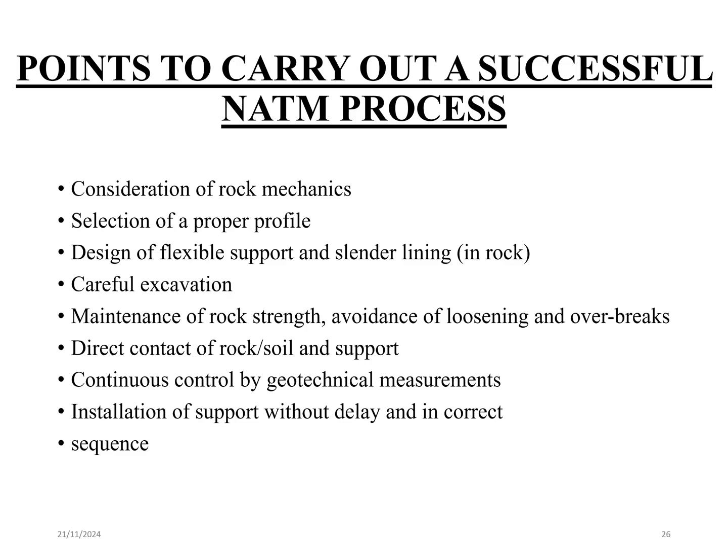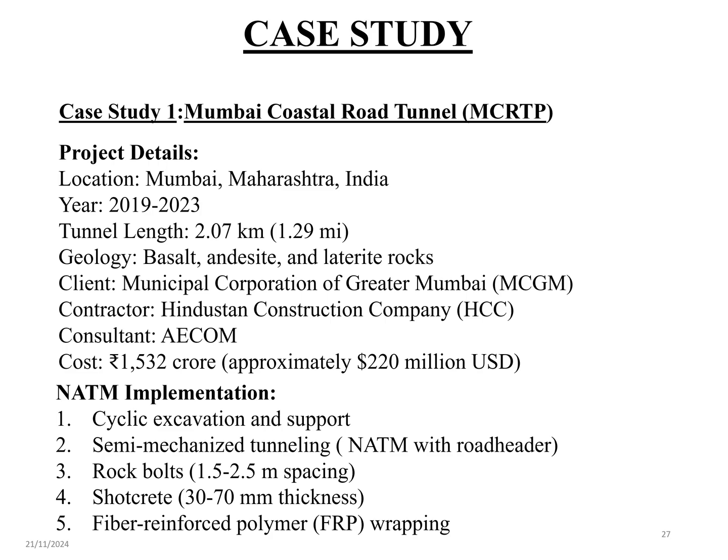Ensure direct contact between the rock or soil and the support system. Implement continuous monitoring and geotechnical measurement to assess the tunnel stability. Install support systems promptly and in the correct sequence. Now, an in-depth analysis of the project to understand its complexities and implementation in real-world scenarios.